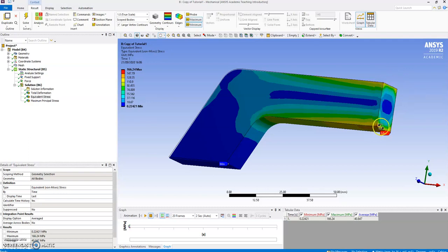So there is no effect of the Poisson's ratio. There are some possible artificial constraints. So we would need to carry out a stress convergence study here, a mesh convergence study, improve the mesh, ideally improve it locally, to check whether that is actually a real stress or an artifact. But even though it has decreased quite a lot, removing that cut has made a large effect.